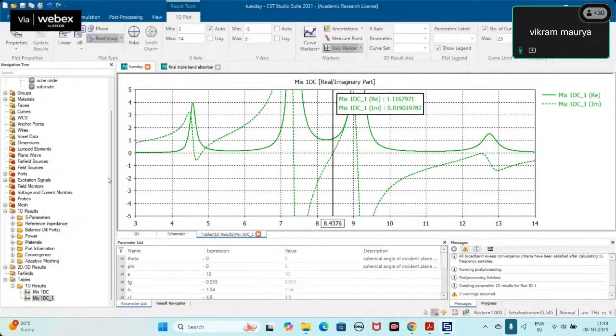First, the result you find out is your S parameter, then go to the post processing, put the exact formula for your S parameter, but make sure it does not contain its magnitude part. It's not containing its absolute part. It should have both components, real and imaginary, because the impedance is a complex term.